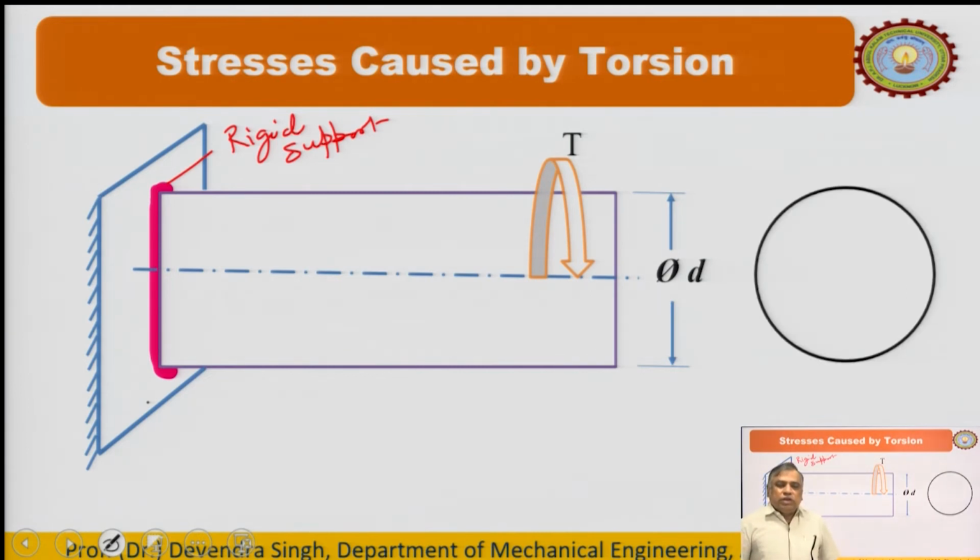So, this is the cross section, and when we move from the axis, if we consider this a plane and this is the center of the plane and the other plane is this, this is trying to move like this. It will rotate about it. So, here the stress is 0 and the resistance to maximum deformation can take place on the outer fibers.